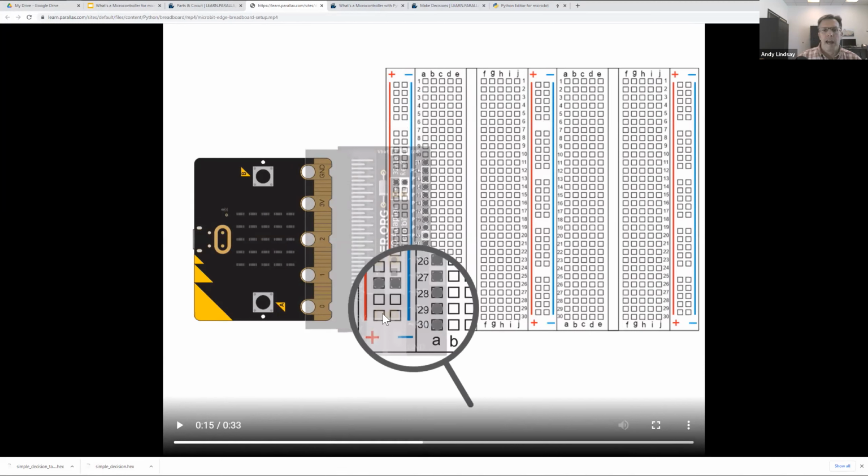What you want to have on the bottom is the P0 pin, the pin with P0 and the label next to it, in the A30 socket right here. And then everything else should follow. All the rest of these connections, just line it up first and make sure that you've got it nicely aligned so that these pins are resting in the plus and minus sockets there.